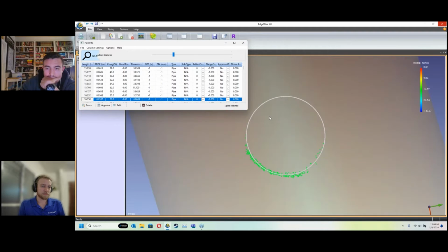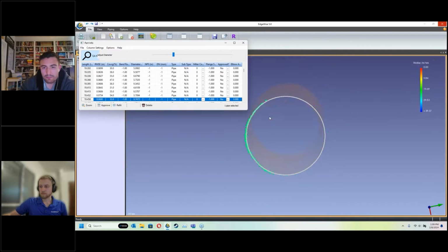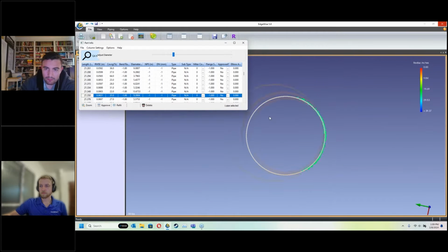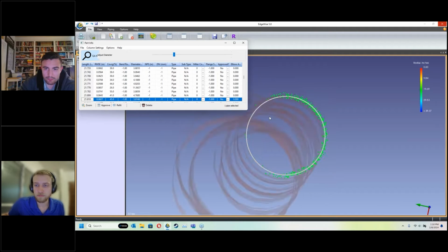Yeah, so the workflow on a data set like this is pretty simplistic. You're basically going to be wearing the device. I actually don't know if they tied into coordinates or not, but definitely you can and probably should in an industrial environment. And then they're just going to walk through the scope, maybe do some pre-planning beforehand and identify areas where they'll create loop closures for the SLAM technology to operate on, and then walk throughout the scope, traverse at grade, and then each elevated platform therein and tie it all together.